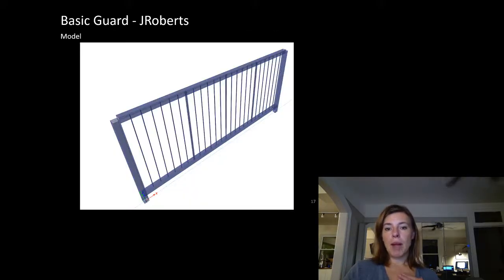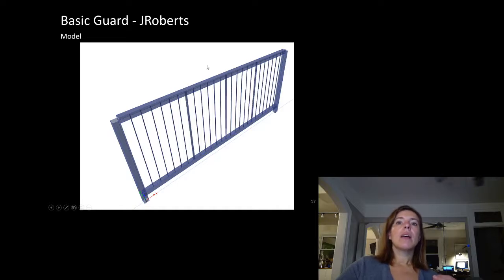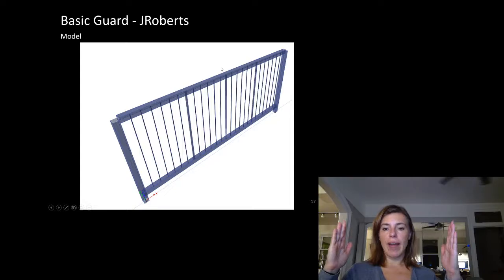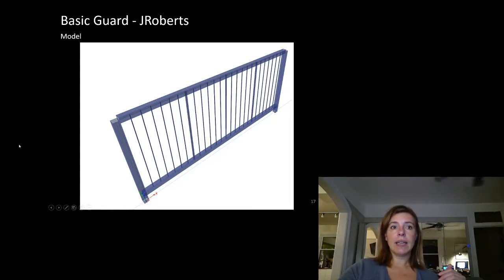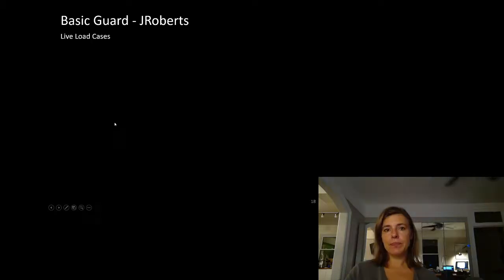So I built a model in my modeling software, remembering that it's not for graphics. It is all about applying loads and seeing how the behavior works. I didn't model multiple segments because the worst case for the post was going to be the 1 kilonewton point load acting on it right here. There could have been a worst case if those were longer and the sum of half of this side and half of this side made for a worse point load on the post, but it didn't.